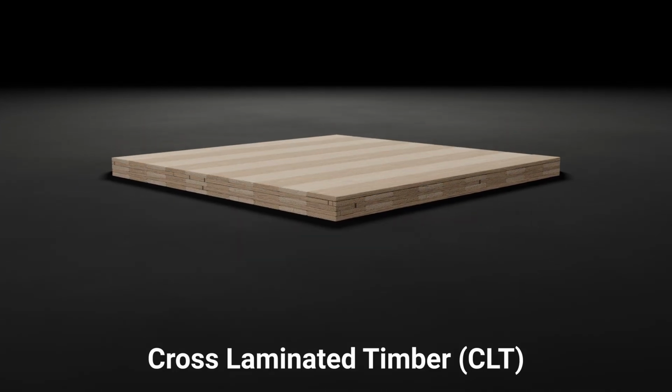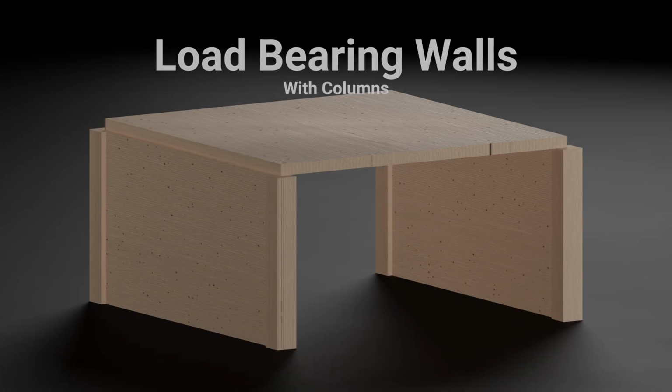Load-bearing walls are a fundamental mass timber framing method used in construction. Unlike other framing methods that rely on columns and beams, this system uses structural walls to support both vertical and lateral loads. The walls, often made of engineered timber like cross-laminated timber, serve as the primary structural elements, distributing forces efficiently across the building. The result is a stable, durable, and even well-insulated framework. This method can be used independently or in combination with columns for additional support.